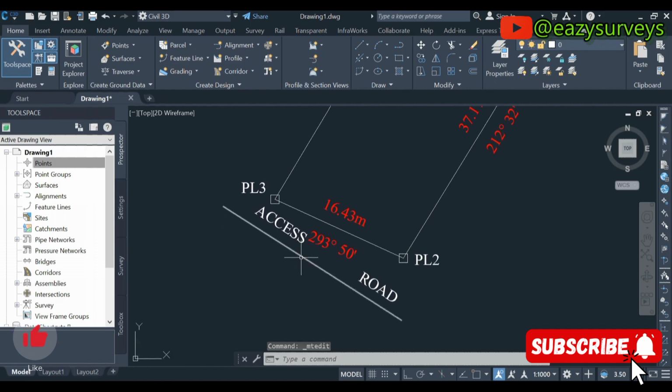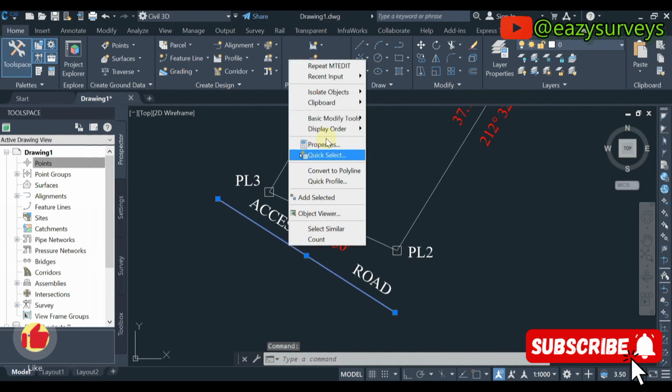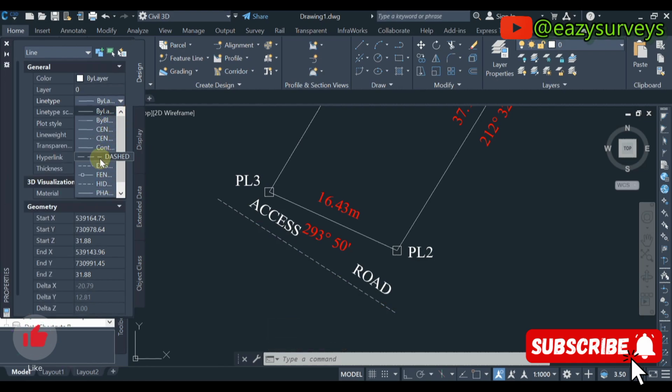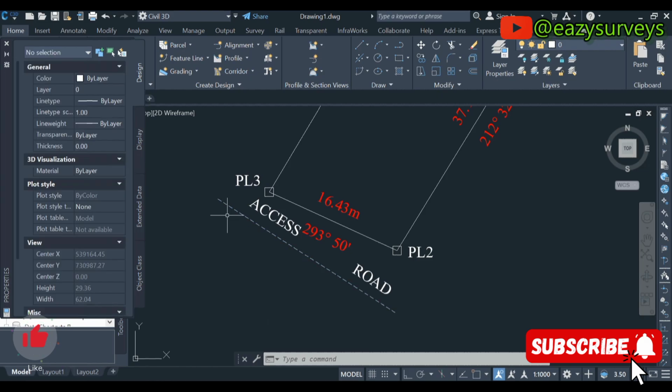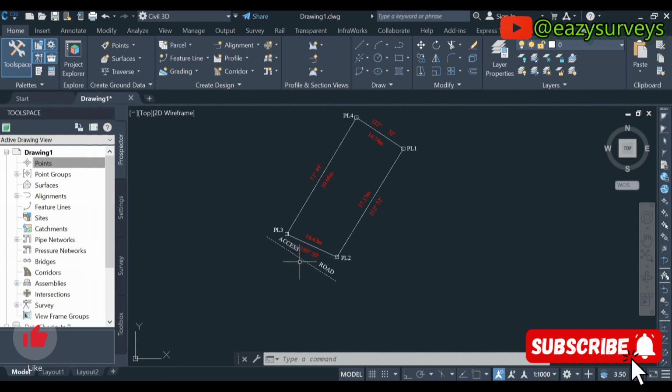So this is expected to be a break line. All right, this line for the road. So you click on it, right click, come to properties, you click on that, you come to line type by layer here, you click on this, you are going to see some options. So you are going to see dashed and dash 2 depending on what you want. So I'll go with dashed. All right, so that's just how to break the lines, and that is for the access road.